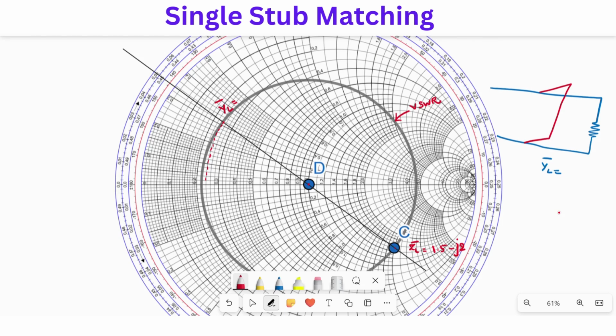To find the real part, you have to track the resistance circle, and the value is 0.24. So the conductance value is 0.24 plus j, and we have to follow the reactance circle, which is right here. The value is 0.32. So YL bar is given as 0.24 plus j0.32.